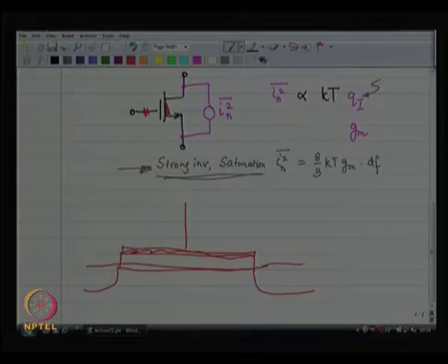So, maybe the contact is over here, and when you, let us say, apply a pulse voltage on the gate, all of this charge has to travel through considerable amounts of resistance to spread around all over the gate, right.